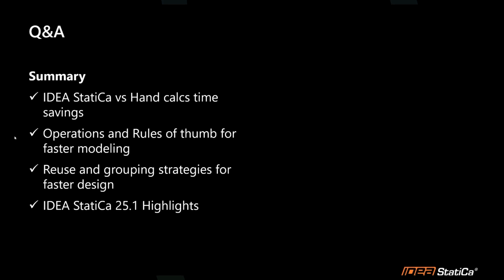What about, there's a question asking, are we limited to only using parametric connection modules or templates, or can any type of connection be modeled from a combination of cross sections, welds, bolts? So basically, are they limited to the initial templates that are shown in the app? No. So these templates are just a way for you to get started. So once you open any template that you find, you have the availability of adding more members, removing members, adjusting the connections, removing parts of the connections. So again, it's just a way for you to get started.